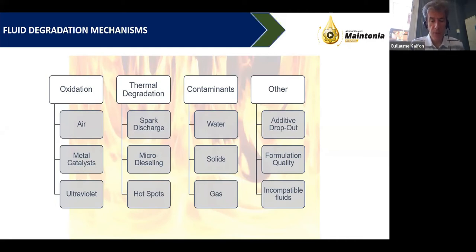And sometimes you cannot really eliminate all the solids. You can also have solids which come from poor flushing on commissioning, where you leave some solids behind, or wear anywhere inside the machine will turn into metal particles which are solids. So any presence of contaminants in your oil